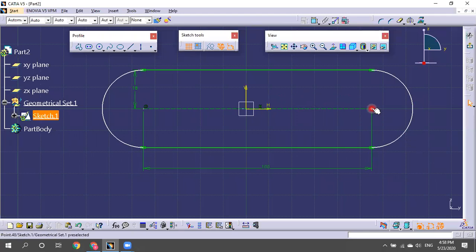Select this point first, right? I selected this point, see this point. That means first select this point, then select this line and make a symmetry. These 2 points will be symmetric with reference to this axis. That's the meaning. So what I'll do now is select this particular line. Use the control key. Don't forget, use the control key.